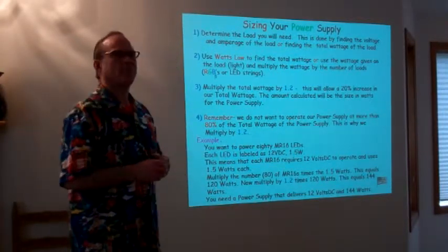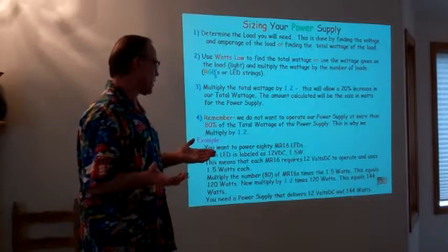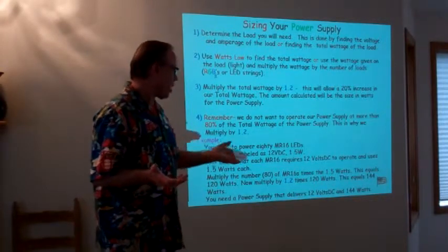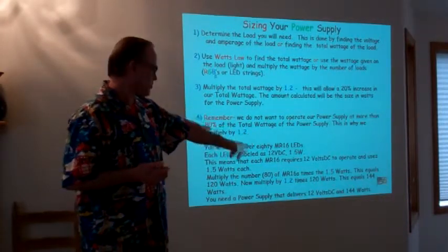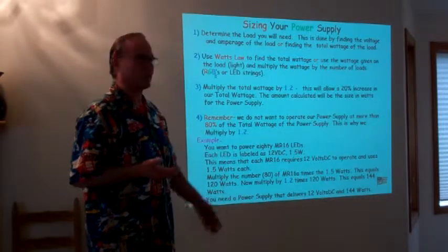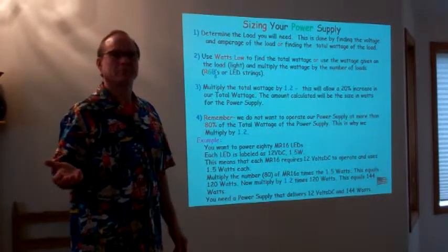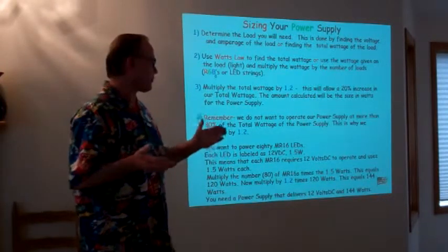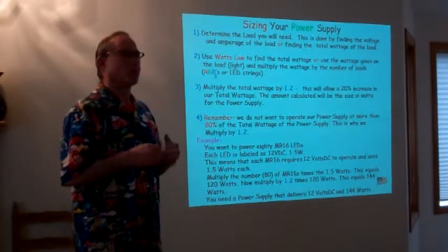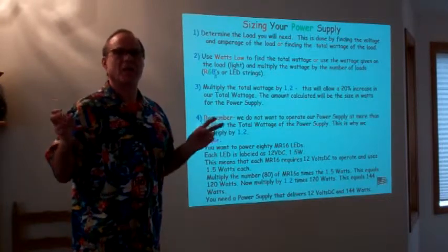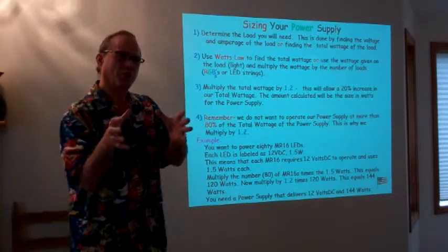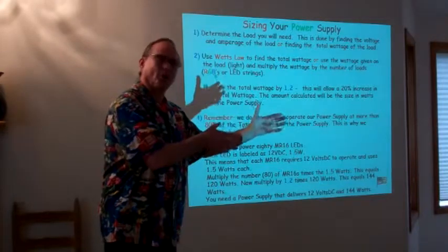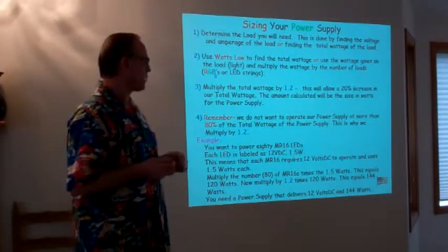with 144 watts. Now, if I wanted to figure out what my amps were, all I need to do is divide my watts by my volts, and in this particular case, that's going to work out at 12 amps. Okay. It's important for us to understand this ratio of amps and volts and watts, because we're going to need to do something like hook things up. We've got to get from our power supply next to our load, and that's the next section we'll be taking a look at.